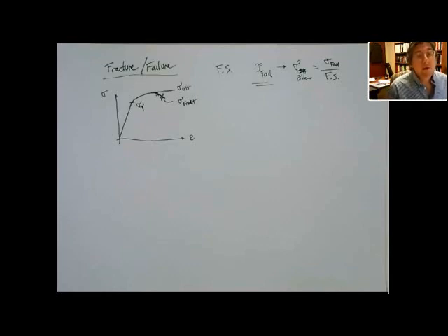Now, if you're talking about designing a B-pillar or a crumple zone in a car, in fact, it's not. It might be the fracture strength, because you don't care that the element plastically deforms. In fact, you want it to plastically deform, but you don't want it to break, right? You're not going to reuse that car once you run it into a wall, right? So for that particular design, the fracture strength or the ultimate might be your criterion. So it depends upon the design, right?